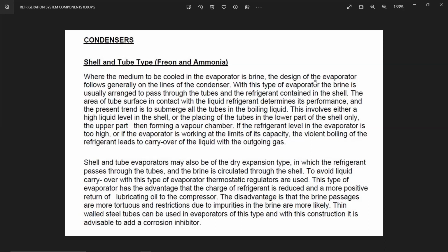You would need a very large volume of the solution, and it becomes a little bit more expensive, because glycol, ethylene glycol, is more used as an antifreeze than actually as a brine. Because it is quite expensive, I think, as it is. So you can have a saltwater brine, which is cheaper to make, but the problem with that is obviously corrosion and everything. So you have to have the system designed that way.